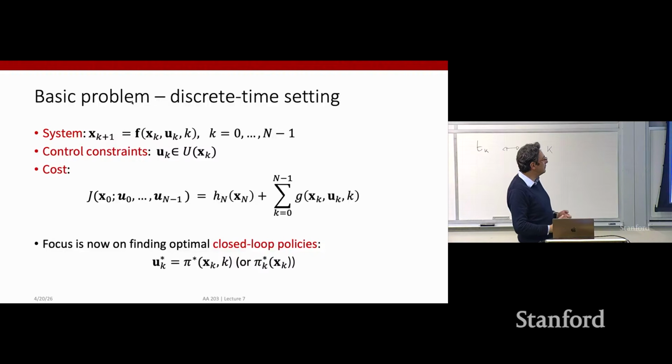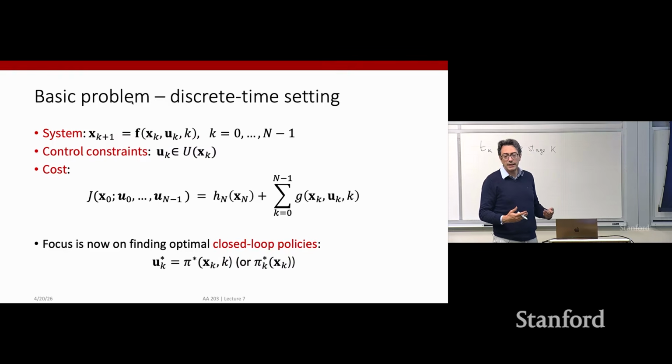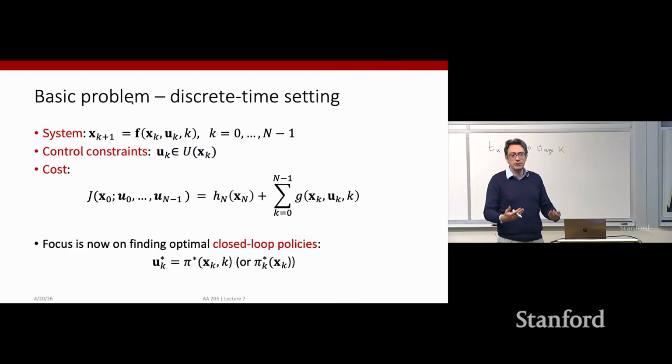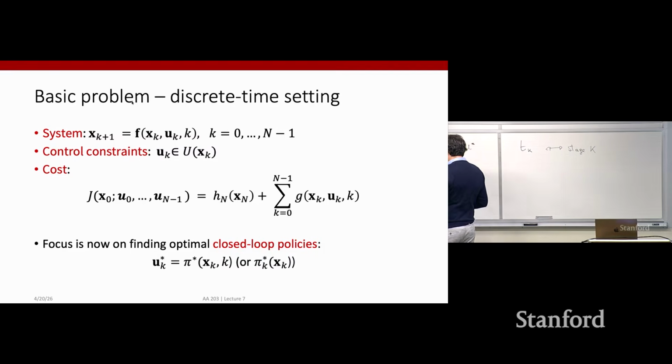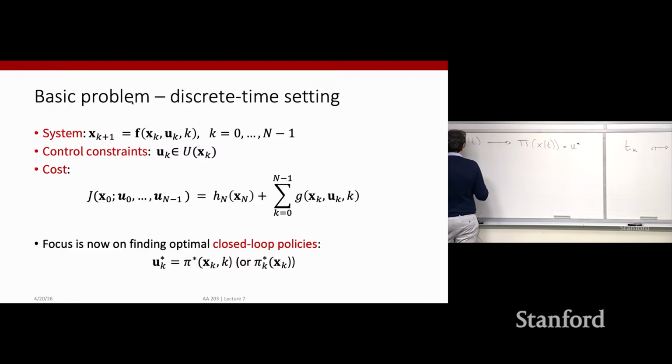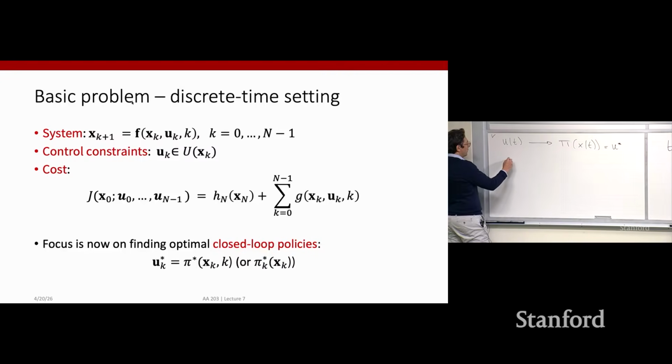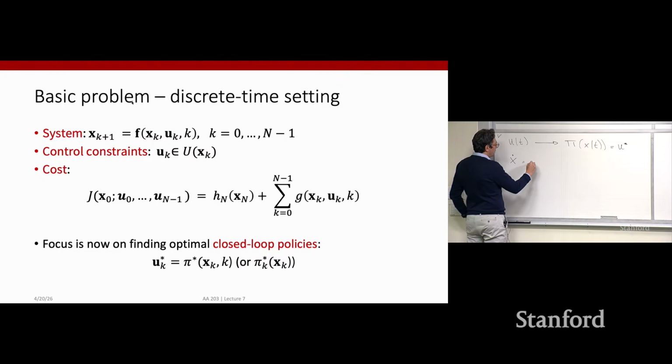Now what we have is a discrete time equation, which can either be derived from the continuous time equation through discretization, or maybe it's just the most natural way to define the dynamics for your system. But in case you derive it from the continuous time equations, one very simple way to go from a continuous time update equation to a discrete one is through Euler discretization.